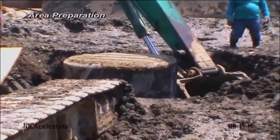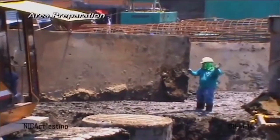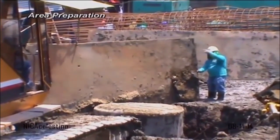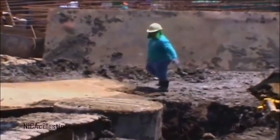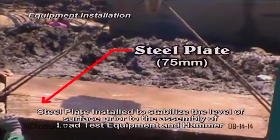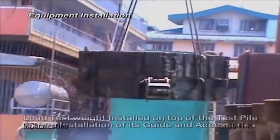The PDA test is one of the important tests that is carried out to check the load-bearing capacity of piles. Firstly, the pile should be hacked until it reaches the sound concrete and built up to the required level. After the concrete has gained the required strength, the PDA test is performed. Firstly, the cushion surface is prepared on the pile by keeping plywood or steel sheets on the pile surface, and drop weights are placed.